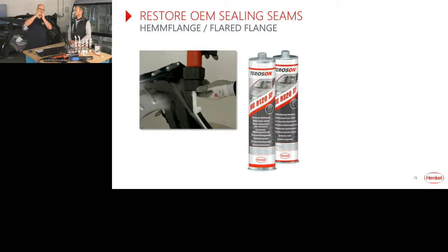No? Okay. So you have a panel here, it's bended on a round angle, and from one here, you put them together and you have a small gap. So you fill the gap and seal it with the 9120, which is more stiff. And after that, you can spray wet on wet with the 9320, a next layer on top of it. Okay. So if you would use only the 9320 to spray, it will sag down into the gap, okay, and then it doesn't look nice.